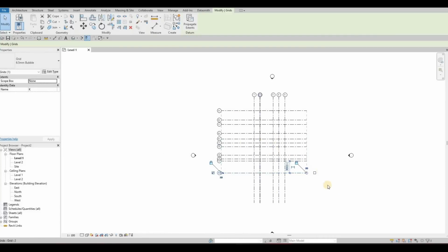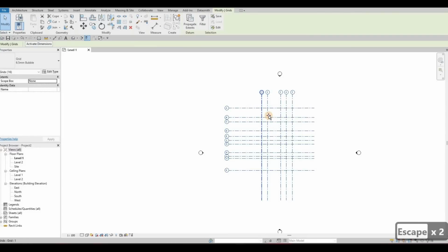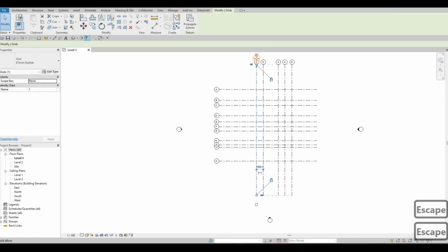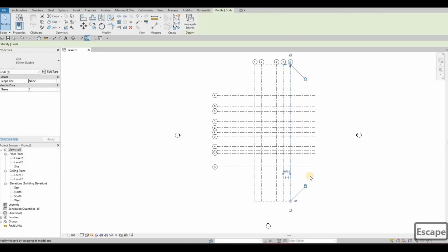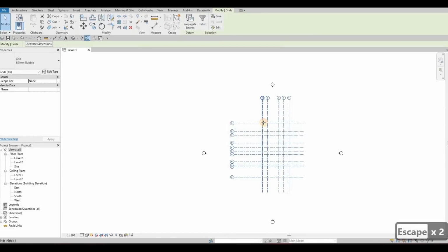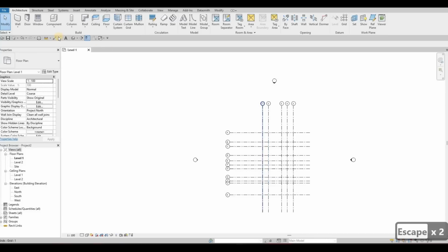And then we're going to maybe add more rooms at the top because I'm planning on adding dimensions that will help us. So here I could stretch this, and as you can see, everything follows along. And then we could even make this one shorter because we don't need that too much. So here, let's just move it to the center like that. Press escape and then escape again.